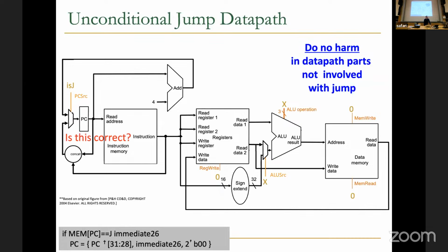Not exactly, because it's not completely correct, and this is a mistake that you may make when you design this. I mean, it's correct in the, let's say, high-level sense, but it's not correct in the sense that we got the wrong program counter, right? The instruction specifies, remember this crossover here, it's not the program counter. It's not PC. You should get PC plus 4. That's the specification of the instructions at the architecture level.